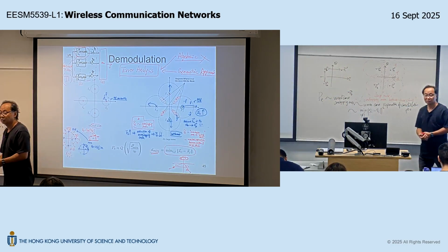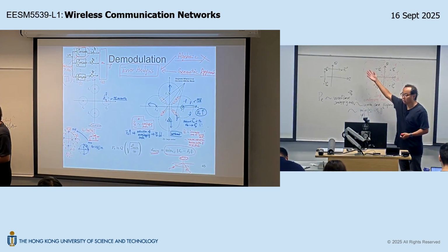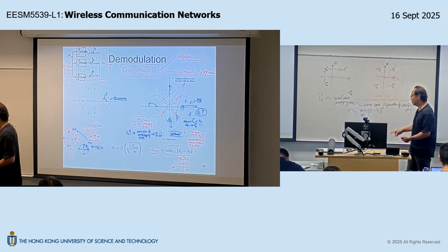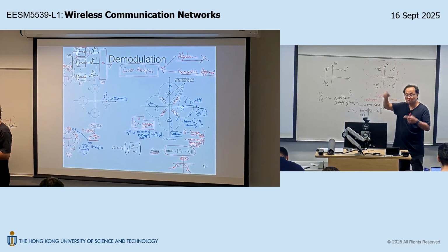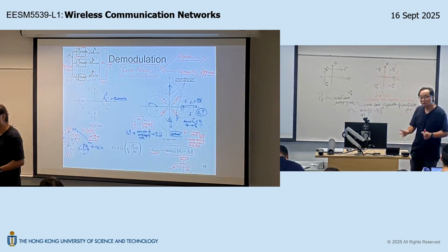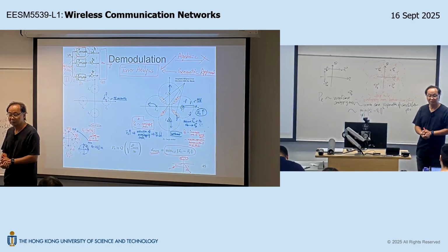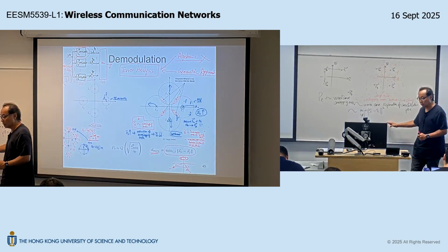Is that okay? So always address the bottleneck. And the bottleneck in an M-ary modulation is given by the worst case separation between any two noise cloud centers. Any extra energy should be spent to address the bottleneck. Okay? So keep this in mind.